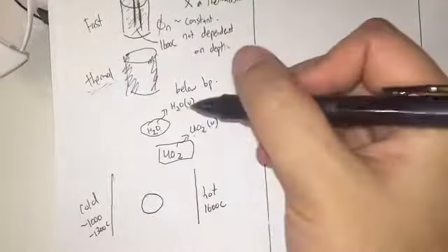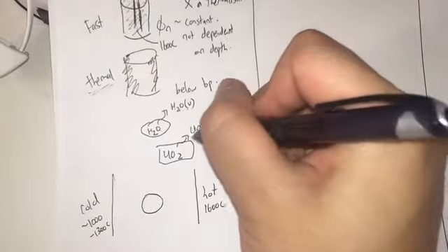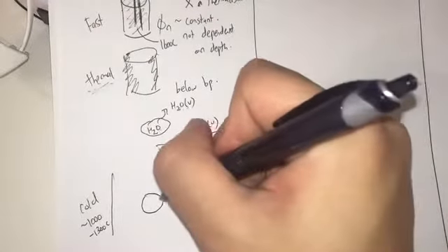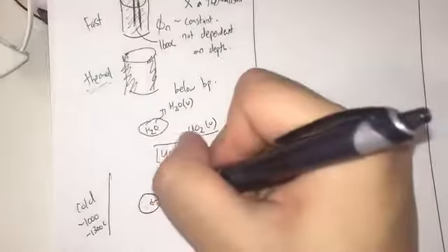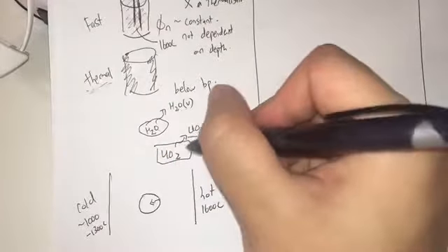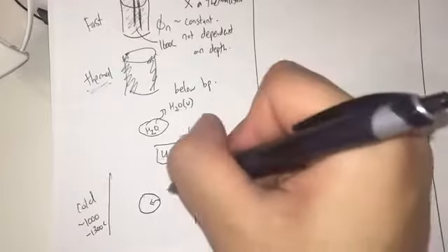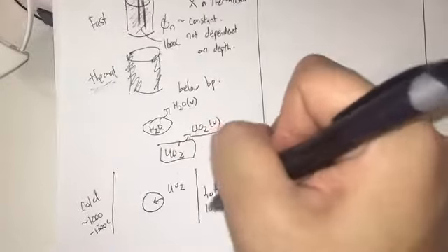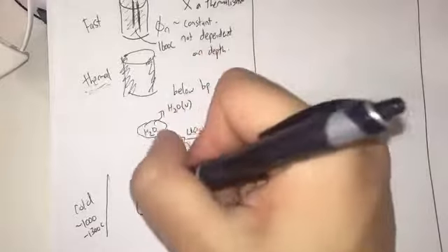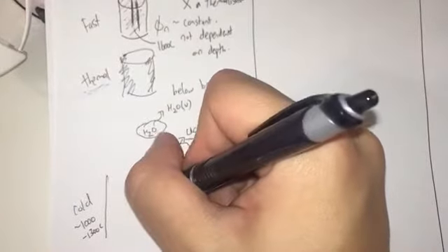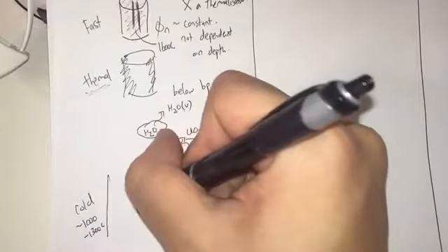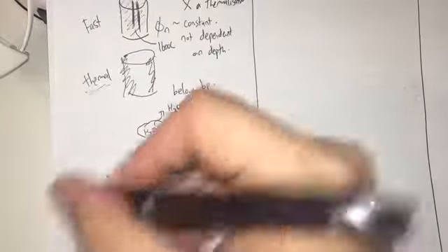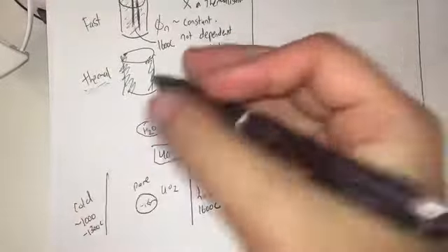So what happens here? Well, there's a little bit more evaporation happening on the hot side. So there is some vaporization of this uranium oxide at the hot side here. And this vapor will diffuse in the pore, and then it meets a colder temperature, this 1000 degrees.